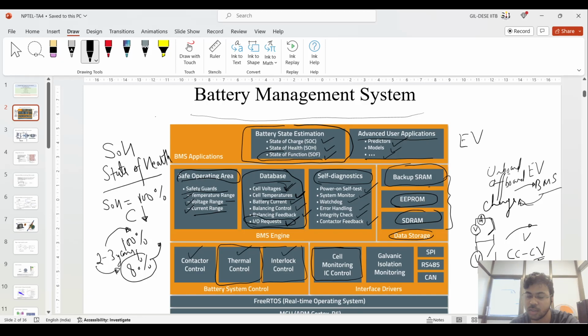There are certain modes of charging, there is the CC/CV mode. If it reaches the CV mode at 100% or 80% SOC, you can switch off the charging so that it cannot overcharge the battery pack. And the other is galvanic oscillations. We will discuss this galvanic oscillation later.